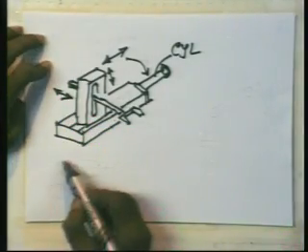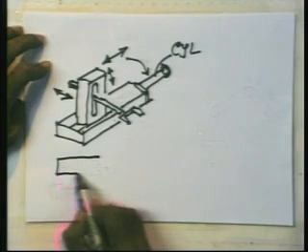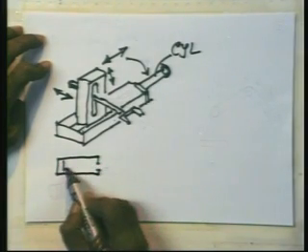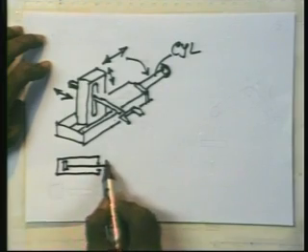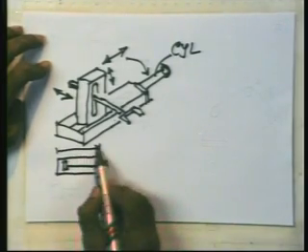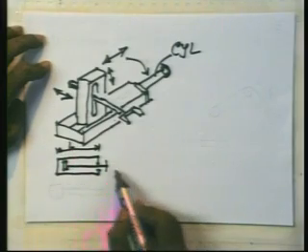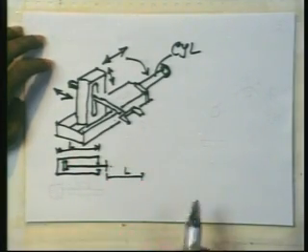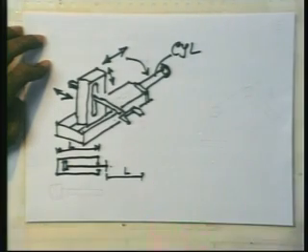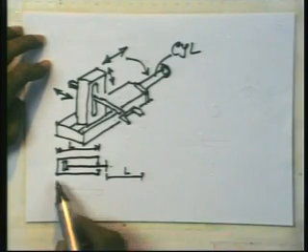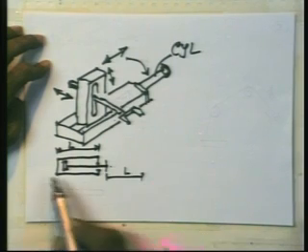So when you have a pneumatic cylinder like that, let us say the cylinder length is L. I have this pneumatic cylinder, there is a piston in it, and if this cylinder length is L, the stroke is also approximately L. So if the pneumatic cylinder moves in and out, and you get a cylinder length of L, overall space occupied by the pneumatic cylinder is 2L.